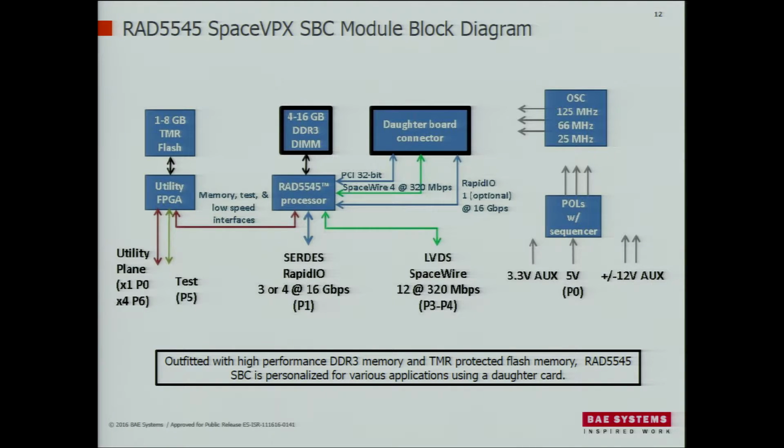The RAD55xx silicon is a 45 nanometer radiation hardened technology, and we got first silicon in the middle of 2016. So this SBC is our first board design that uses that device, and that's in or just out of manufacturing as we speak. If I was back home, I might be getting yelled at to go down to the lab, I'm not sure. So at any rate, this is our first design that uses the chip. It is a space VPX single board computer.